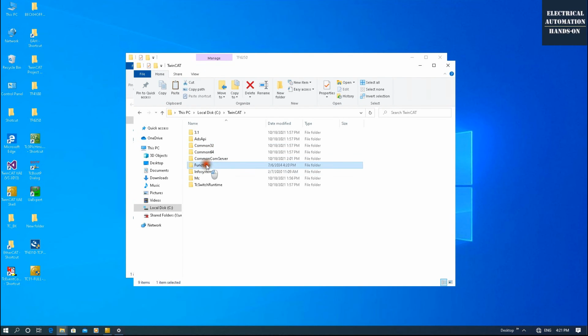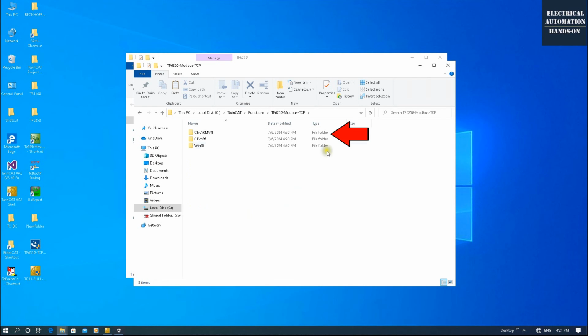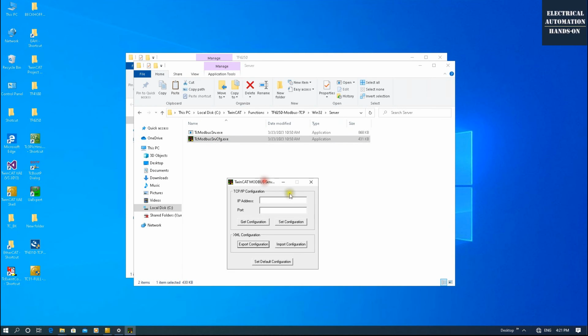After the installation, let's go to this directory. As I introduced, if your target PLC is using an x86 or ARM platform, you need to copy these two folders into your target PLC and run this CAB installation file there. In this case, I'm using the PC as my Beckhoff PLC, so it doesn't matter. I can directly install here.